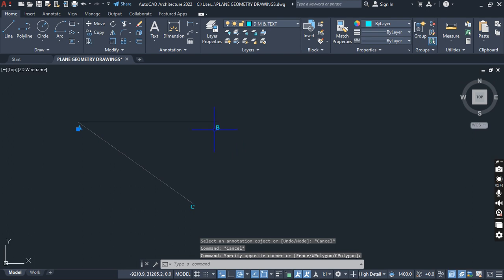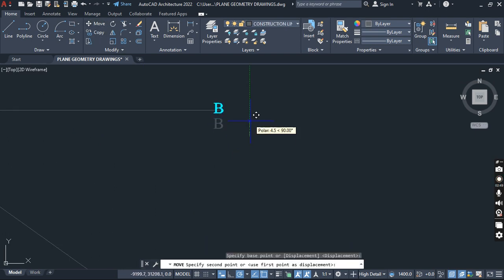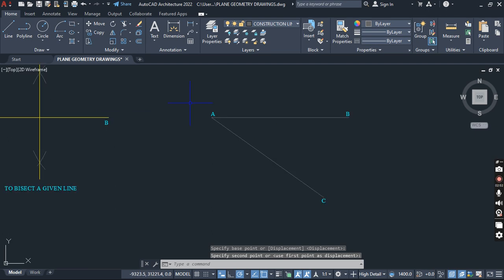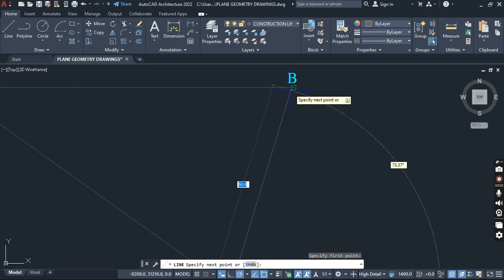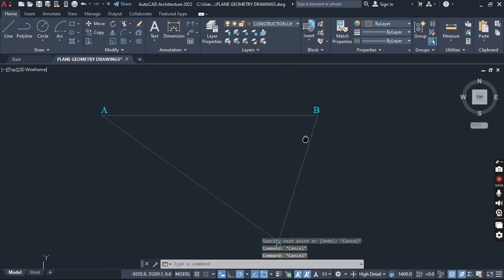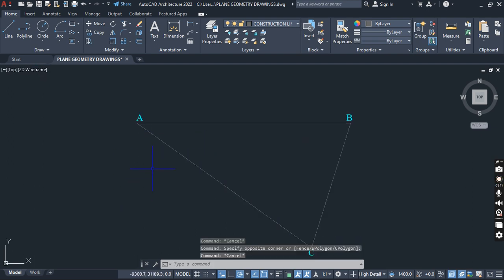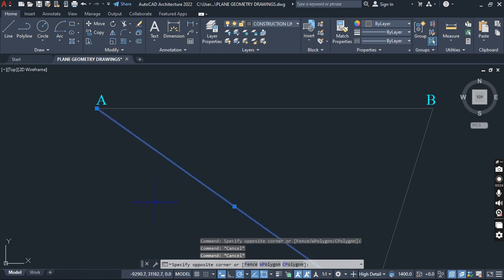I'm going to put these above the line. So I highlight them and I move. All right, so putting them above the line because the construction process would have gone in the way. So step 3 is to connect C to B. All right, so we have ABC, basically a triangle. The AC line now, we're going to divide the AC line into 10 equal parts, and then we transfer that division all the way up to the AB line.